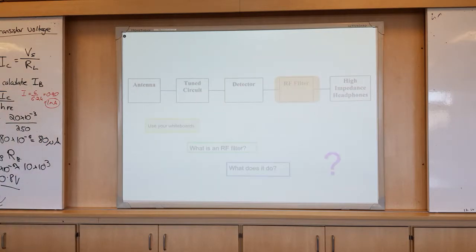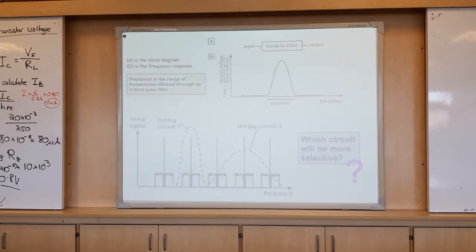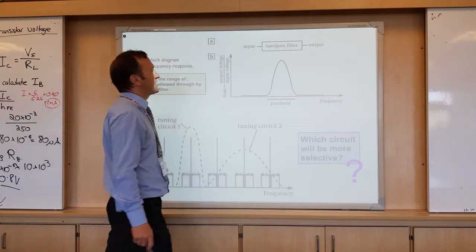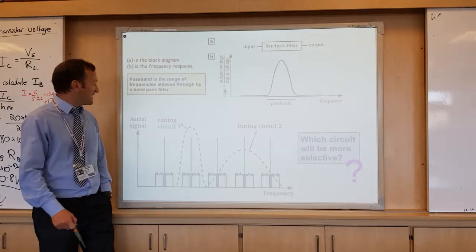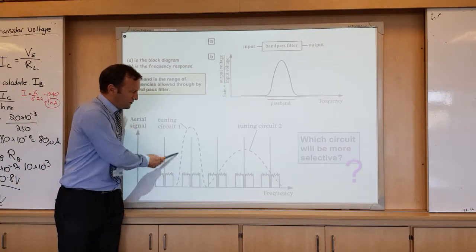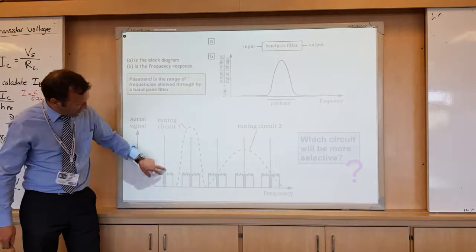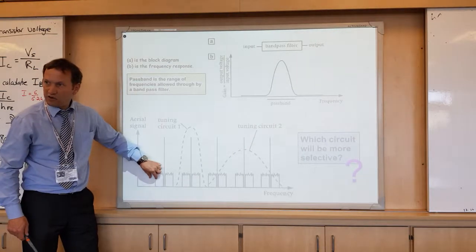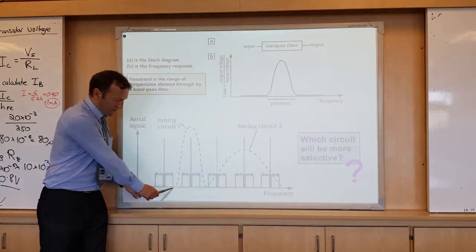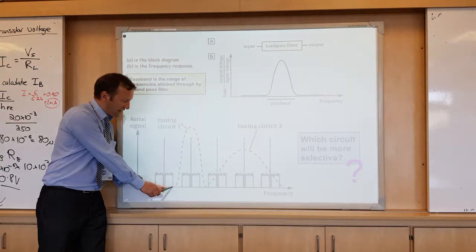So we've gone through this, gone through that. Okay. So, looking at Q factor, if you've got a radio receiver which has good selectivity, it will have some sort of frequency response like that, which fits perfectly over the radio station. This could be Radio 1. We've got the carrier in the middle, and the upper sideband and the lower sideband. The overall bandwidth is always double the individual bandwidth of the signal that you're trying to send.